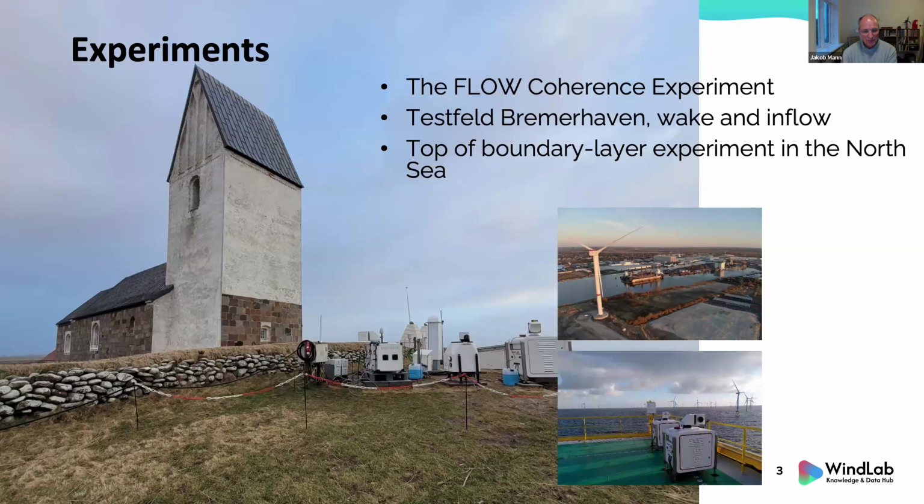In order to improve models, we need experiments. So the project also contains some experiments. One is fully funded by the project. It's called the Flow Coherence Experiment. You see a picture here with a number of lidars, and they all look out over the ocean, the North Sea, and measure in several points simultaneously to look at wind variations, how they correlate within a rotor plane in order to produce better inflow models.